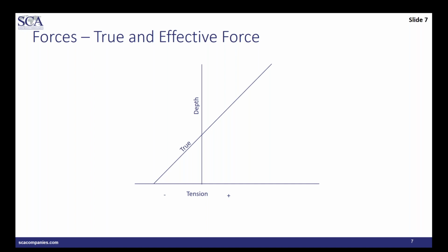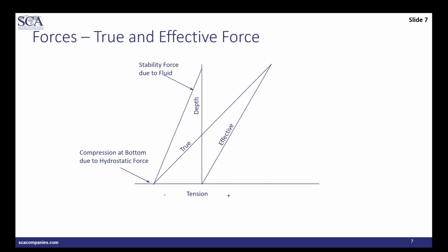But we are not just dealing with that. We are dealing with the system in a fluid-filled system. So we have to see the hydrostatic forces. So you can see here compression at the bottom due to the hydrostatic force. Now, if you take out the stability force, then we get the effective tension. Now, as I said, this is not well understood. We'll reinforce all these fundamentals in the class in more detail.